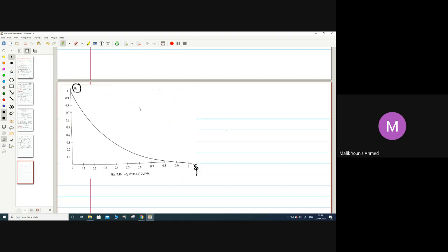While you are controlling these instruments, maybe there is a lot of hunting. Hunting means that your reading is not stable in the process. You can have any type of chemical process, or the food and beverage industry, and the process fluid can be anything, but you are not getting a proper reading. That means hunting is there. In that case, you will increase damping.